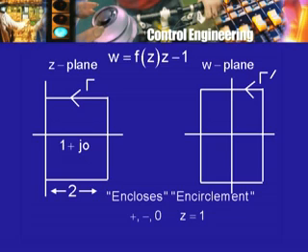So the result here is that I have a curve gamma. There is a point which is a 0 of the function f, which is enclosed by the curve gamma. I have the image contour gamma prime. This image contour gamma prime encircles the origin the same number of times as there are zeros enclosed by the curve gamma. Now this, of course, we just verified by actual drawing for the simple function z minus 1. It holds for more general functions, not too general, but sufficiently general to be of use to us in our work with the feedback control system.